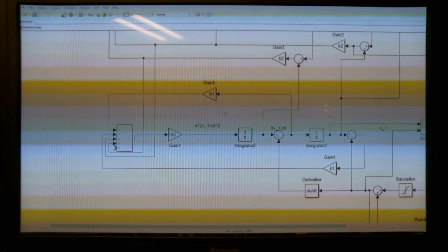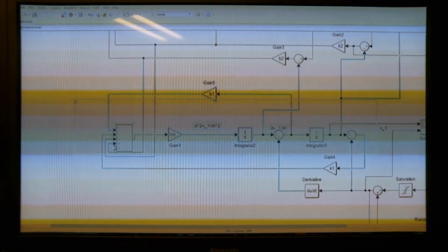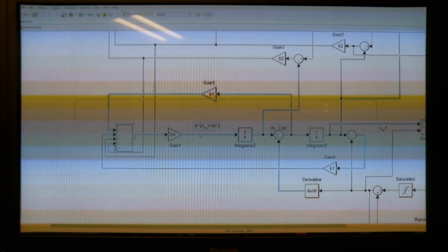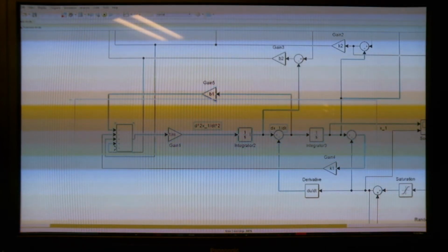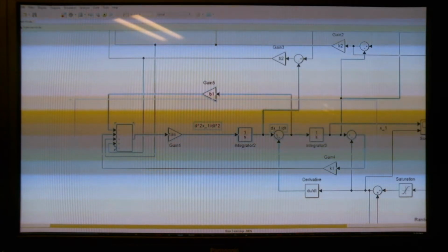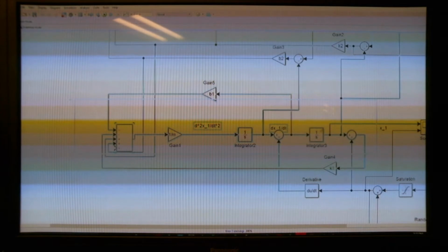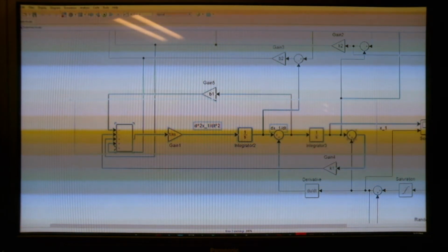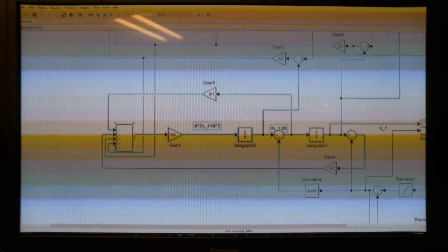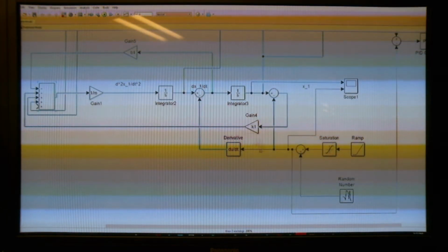As you can see in this, this block is effectively the same. We have a sum block, a gain by 1 over mass to get our acceleration, which we integrate, and after which we integrate again and we get our position. Now we have the interactions added in to create the dynamic model.